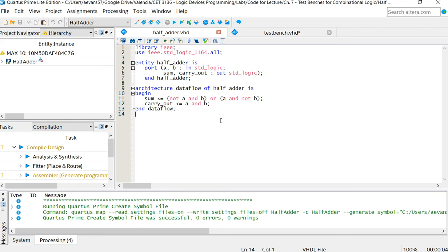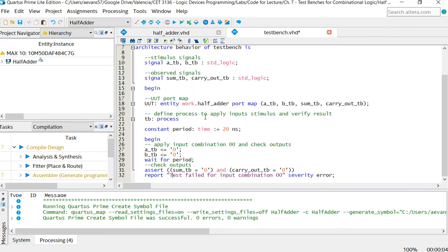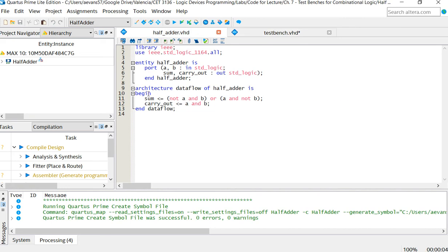A test bench is not a compiler. It's not looking for syntax errors. It's not looking for missing semicolons or incorrect data types. It is looking to see if the logic of the code that was written in this architecture does not hold up to a standard. So if the test bench identifies that there is an error, the code has to be rewritten or examined for a logical error within the architecture itself.